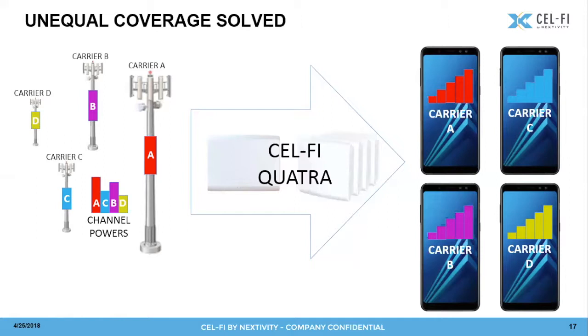There is a maximum, I believe it's an FCC rule, but there's a maximum allowed of input energy where we could actually alarm off of. The survival input is over, I think it's over a watt for Quatra, but we're talking about swamping the front end with energy from a nearby tower. Of course, that could happen. The chances of you having a tower that close to the system is actually, I think I've only seen it once in my experience. Maybe others have seen it more, but it's true. What it would show up for us would be a reduced signal to noise ratio. In other words, it would be handled by the antenna aiming algorithm.